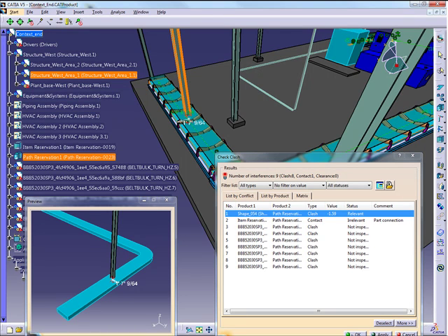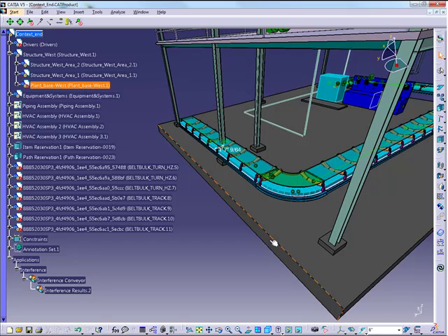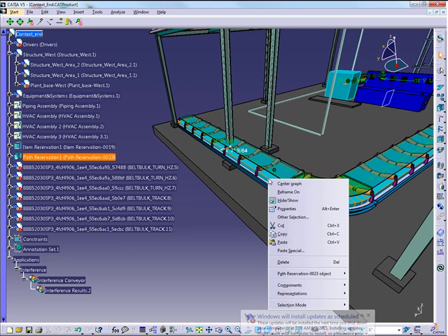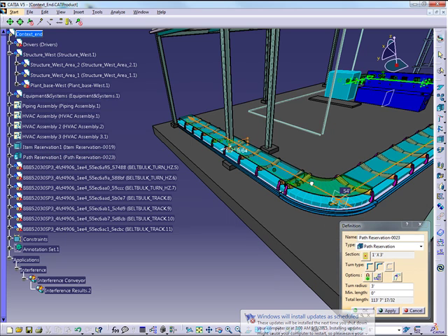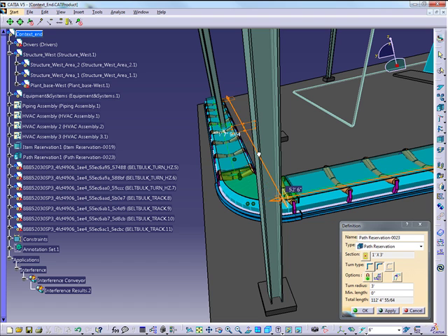Okay, Juan? So let's go ahead and close out of this, and let's adjust the design through the design intent model, the space reservation, and have the construction fabrication model update. Exactly. Just keep in mind that this space reservation has the intelligence to change any construction and fabrication models. So here we go. I am just going to select the space reservation and move it a couple of feet away. I'm just going to turn around the system to make sure that it's free of collision.